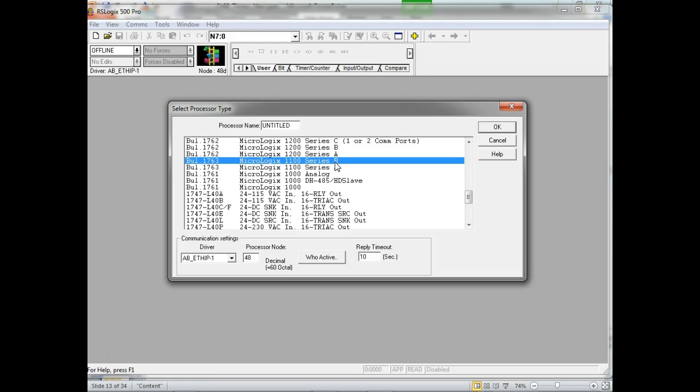Where's the information at? It's on the side of the PLC, right? On the side you cover up, by the way, when you put extra modules out there. So that's something you need to remember. You need to get that number off there before you start mounting modules on the side.